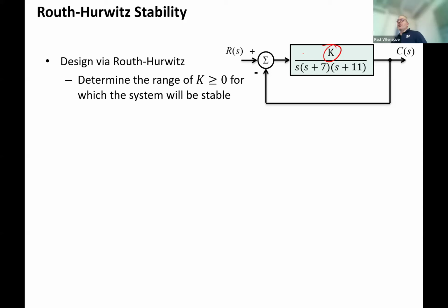One of those criteria is how long the rod length, this lever length, needs to be, and how fast the tank can fill up. It's the multiplication, if you will, of the physical gain of the system, so that if you send in a small 4 to 20 milliamp control signal, what is the output that you would get?